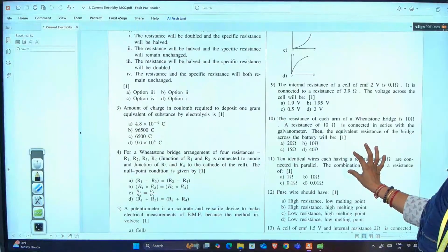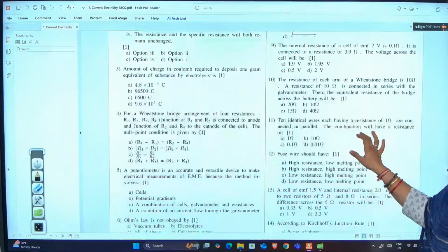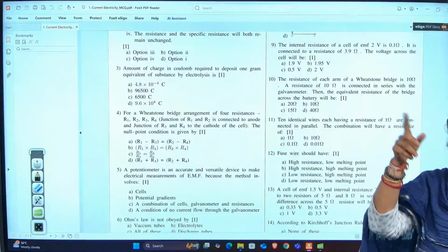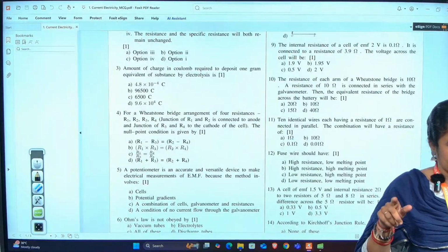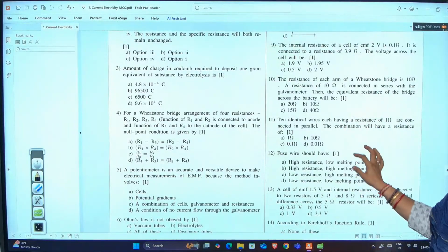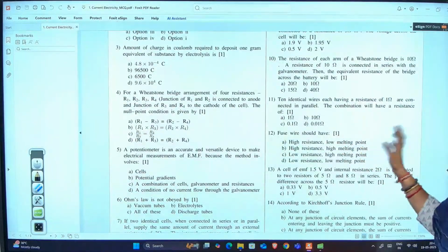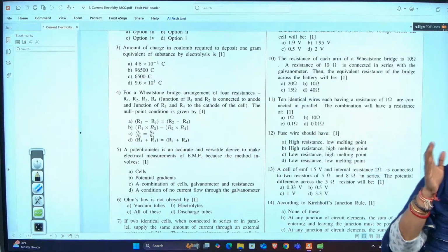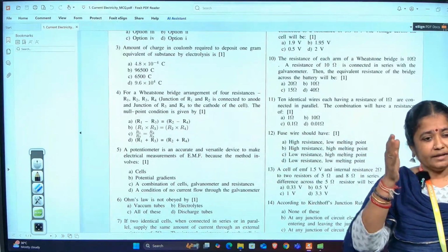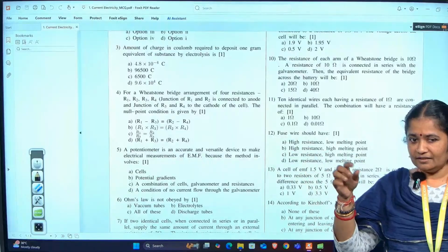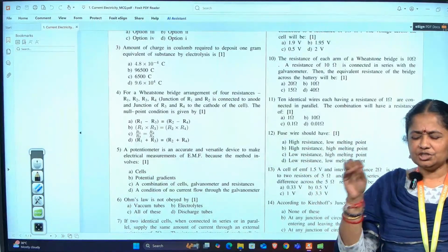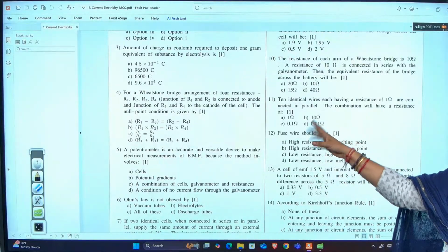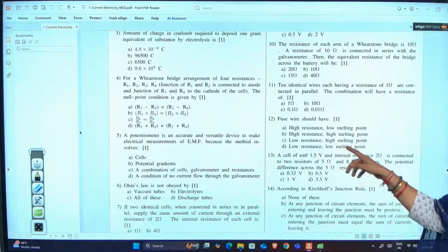The resistance of each arm of a Wheatstone bridge is 10. So the upper 10 and 10 are in series, and the lower 10 and 10 are in series. So 20 in parallel, 1 by 20 plus 1 by 20, 20 by 2, 10 ohms. Two identical wires each having a resistance 1 ohm are connected in parallel. 10 identical wires, so 1 by 1 comes 10 times. So 1 by 10. General equation R by N, so 1 by 10, which is 0.1. Fuse wire should have...